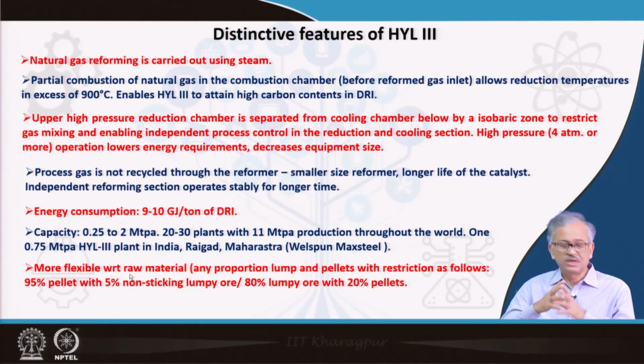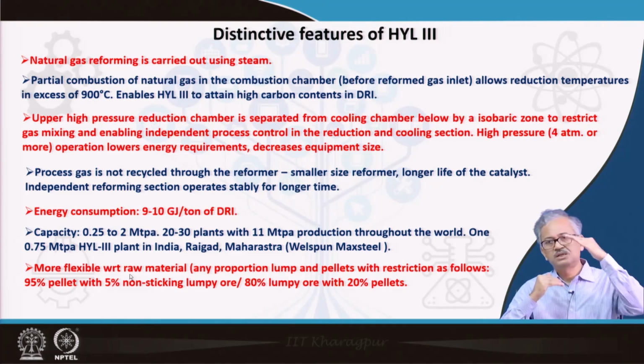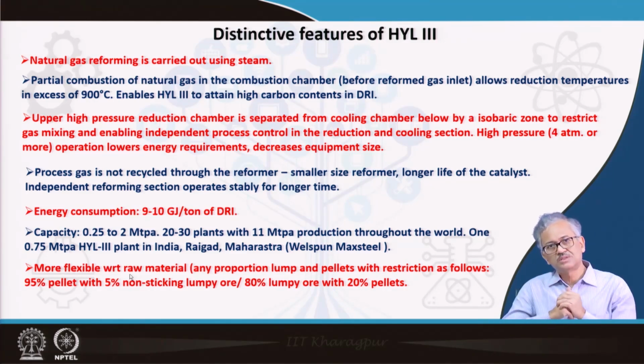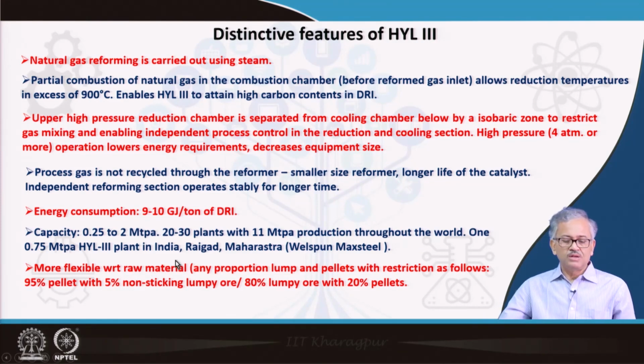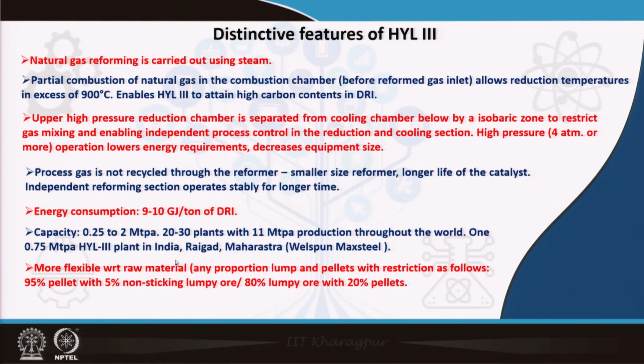It is more flexible with respect to the raw material. You can charge 95% pellets, but 100% pellets is not possible because they have sticking problems. So 5% non-sticky iron ore you have to apply. Then you can operate with 95% pellets, or you can use 80% lumpy ore with 20% pellets, that is also possible. Lumpy ore you can use because the reactor operates at high pressure. So you can compromise on the raw material to some extent, okay.